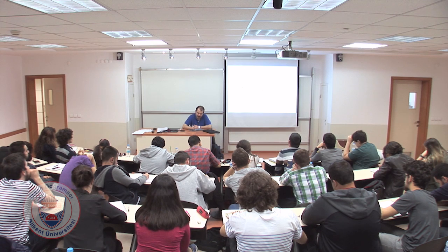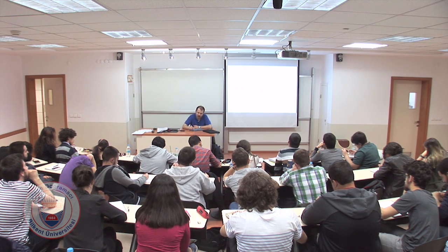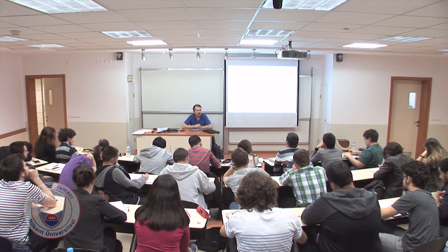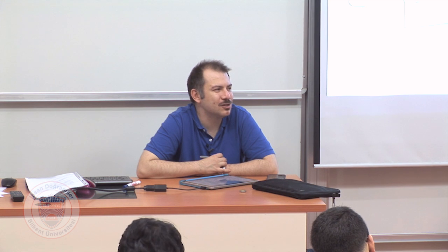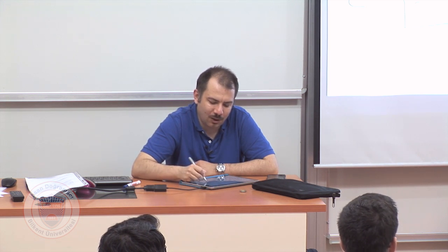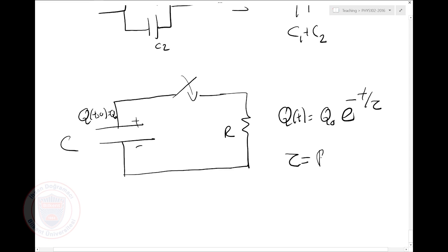What did we find? We find that this discharge follows an exponential pattern, right? We could scare ourselves saying that we are solving a differential equation, or we could just remember that exponential is the only function that's constant under derivatives and integration. So what was tau? Tau was RC, which is called the time constant of the circuit. Generally, tau is what you see dividing time in the exponentials. It doesn't have to be RC all the time, but when you have exponential behavior with e to the t over tau, that tau is defined by the exponential function itself.